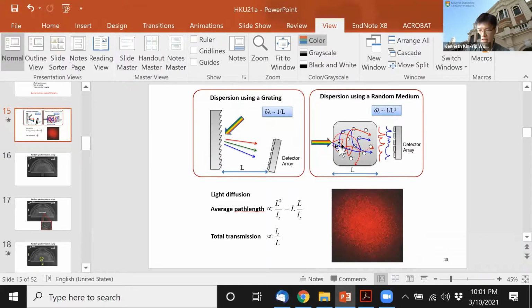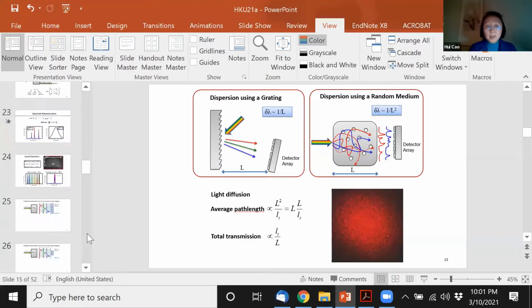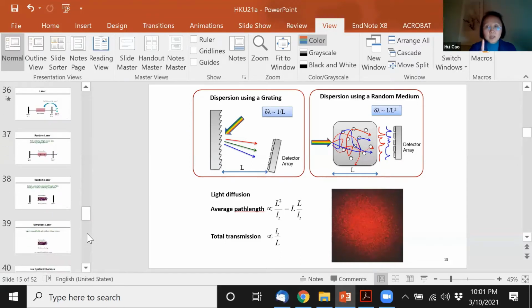Okay, thanks. So the question from Dian Yang is asking, could you talk about using multi-mode lasers for illumination? What are the requirements of their wavelengths and the number of modes? Okay, so when I say multi-mode for illumination, I'm talking about multi-spatial modes, not different wavelengths, because I try to tune the spatial coherence by tuning the number of spatial modes, not the number of frequency modes. Why will this be useful?